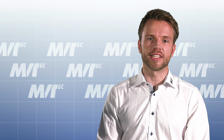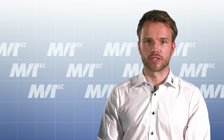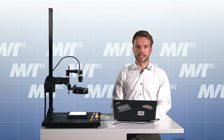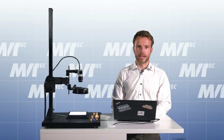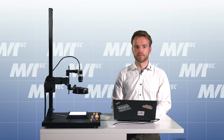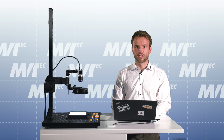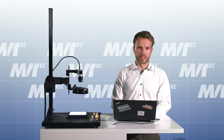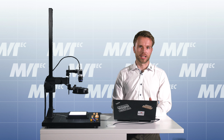The MQTT protocol is an alternative to the popular OPC UA protocol. It is focused on machine-to-machine communication, and it is often used on modern factory floors. MQTT stands for Message Queuing Telemetry Transport and is a lightweight, simple, publish-subscribe network protocol. It is an open standard and an ISO recommendation. With MERLIC, you can use MQTT, OPC UA, or both at the same time.